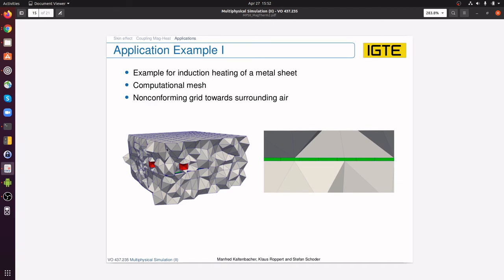So to mesh the air volume with nicely structured hexahedrals is a tedious task, and no one really wants to do it, because it's not the nicest thing to do. You have to split up your volumes into some, let's call it, macro elements, such that the hexahedral meshing algorithm can handle these macro elements and insert hexahedral mesh elements into them.